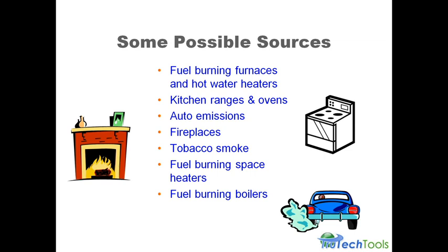Now, there's other sources of CO, and you really got to watch this because I've been caught on this myself. CO can go right through the combustion process. So if you have CO in the house, you went outside, you zeroed your meter outside like you're supposed to, you come inside, you don't test ambient CO in the home, and you're watching your furnace run, and you had 10 ppm of CO come in, it can come right out the other end of the burner, and I've actually seen it happen.